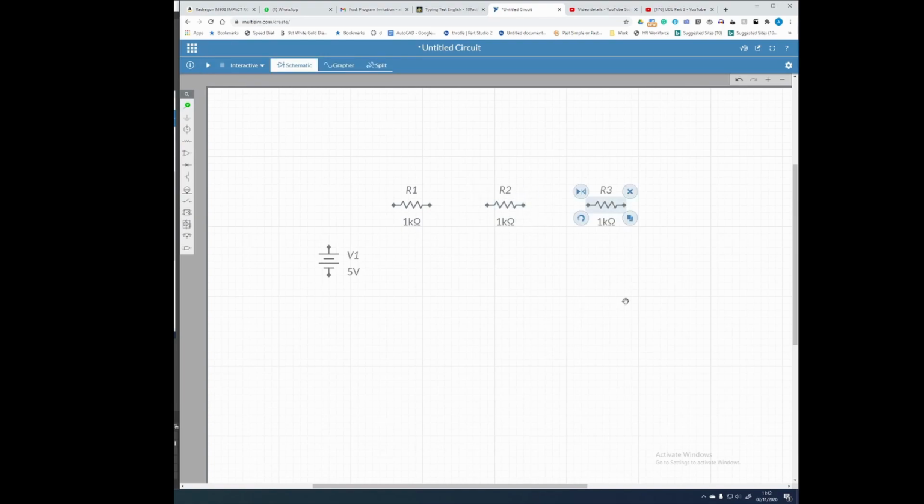Obviously we've got to value them all in a minute. Wire them together. Just wait for it to go to the wire symbol. Click once. Wait till it goes to another and a circle appears there, and click and it'll join. Click. And then now when you have got them there, you can modify them by pulling them down to make them look a bit neater. Pulling it to the side.